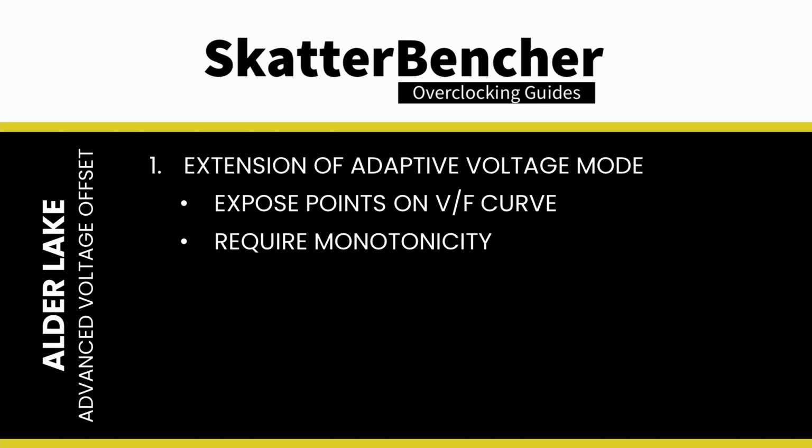The only requirement for the VF curve is monotonicity. Following a monotonic function, as a rule, the voltage for a given CPU ratio must be equal to or higher than the next lower ratio. So, the voltage for 48x must be equal to or higher than 47x.